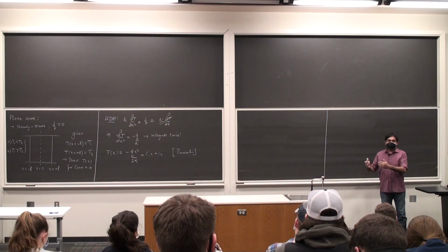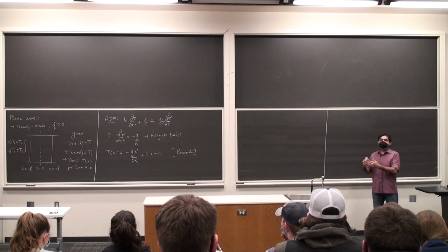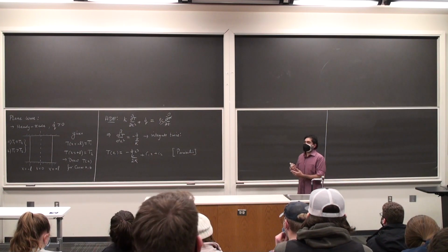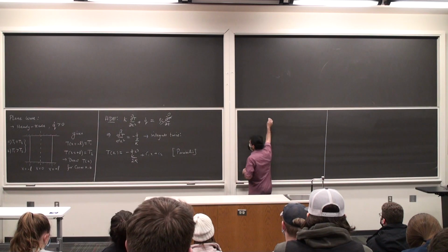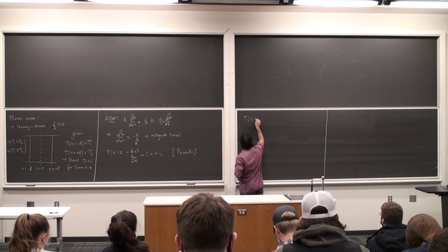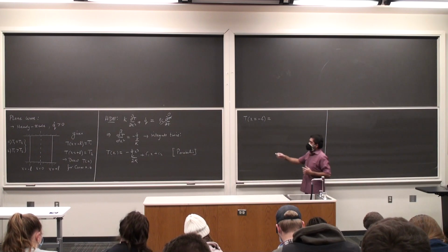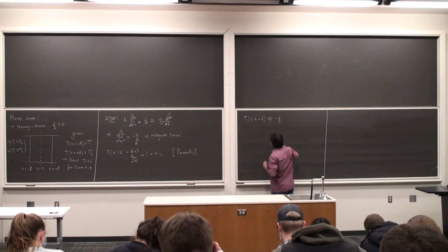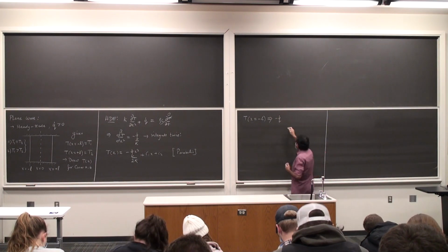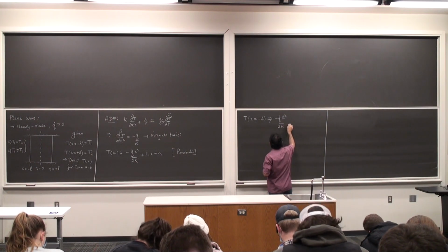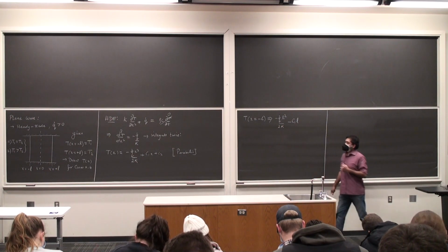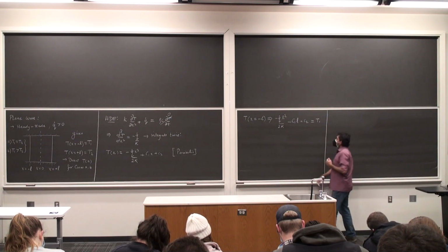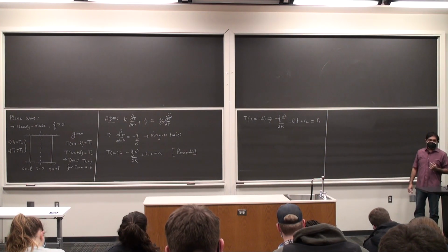What I'm going to do is use the boundary conditions given to me, obtain C1 and C2 in terms of the values T1 and T2, and we will consider each of the cases, and we will see what the temperature profile looks like. Right? So substitute boundary conditions. So T at x is equal to minus L. If I do the substitution, that's minus q dot, minus L whole square is still L square, so this is just L square by 2k, minus C1L because x is equal to minus L, plus C2. This is given to me as temperature T1. This is the first boundary condition.